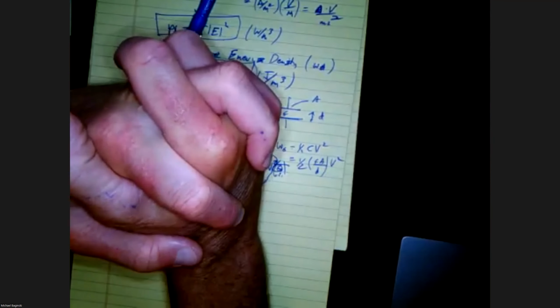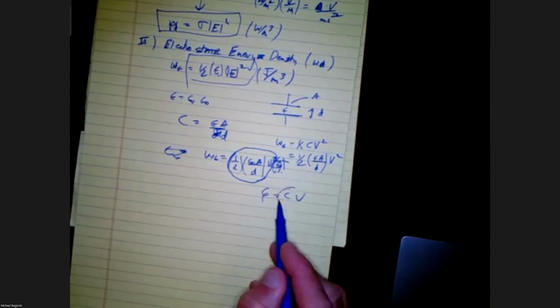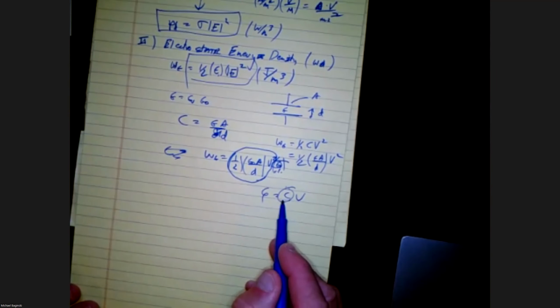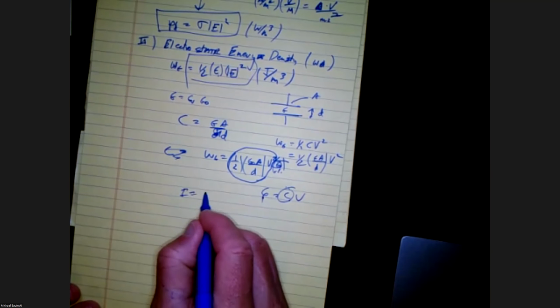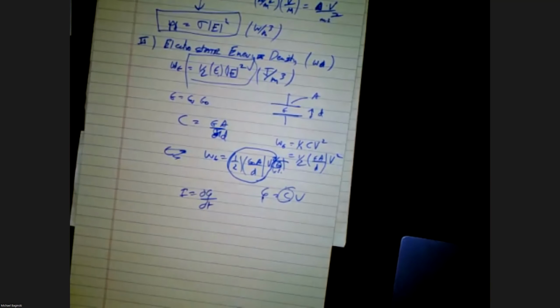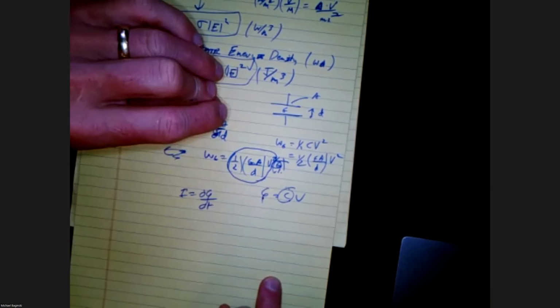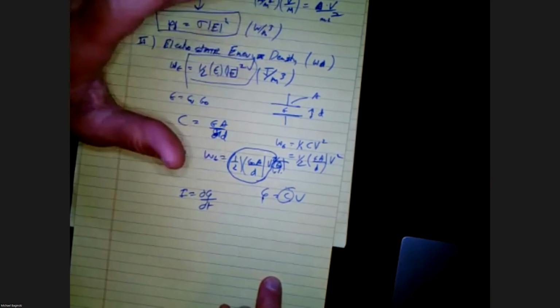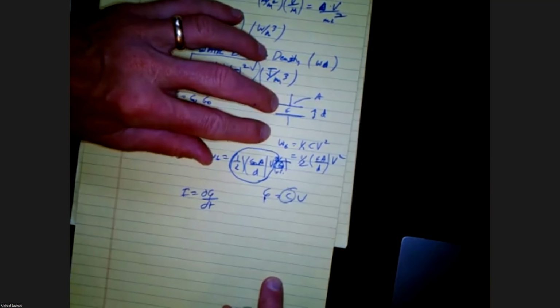Sorry, that's my bad. Charge stored is really going to be equal to CV. Charge is equal to capacitance times voltage. If this thing is huge, you can store a whole lot of charge. And what is current? It's equal to dq/dt. So once you turn the crank on your car, this will be in parallel with your battery, but it'll start bleeding current that will be very large, as needed to start your car in cold weather. That's one of the applications of these supercapacitors.